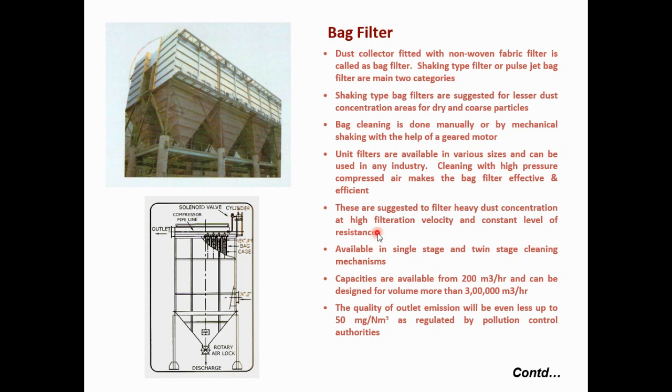Where there is a heavy dust concentration, meaning a large amount of dust is produced at a single point, you can install the bag filter there. But if the volume of air is more but the dust particles are less, then this bag filter cannot be used there. Single stage, two stage, and multi stage cleaning mechanisms are available.